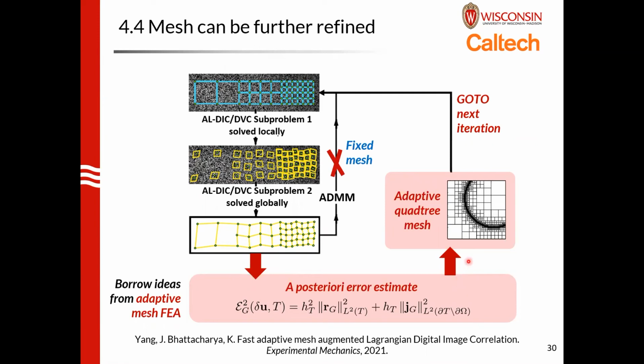That's a good question. First of all, for the Eulerian, we generate the quadtree mesh for each frame. So for every deformed frame, we also have the mask file. The good thing about this is that if you only have one quadtree mesh, the topology of the mesh will be quite different if there's a new crack there. That's why for each deformed frame, we also have the binary mask file and the quadtree mesh.